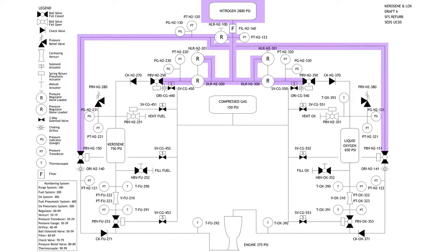When I open that K bottle, the only thing that's going to stop fluids from flowing are ball valves. So you're going to stop at your first ball valve, and you're going to stop at your second ball valve, and then you have two purge ball valves over here. So you're going to have one ball here, one ball here. So that's where your purge gases are going to stop. I mean your nitrogen gas. That's where it's going to stop first. Okay? So that's where it's sitting up against. It's sitting up against all those ball valves.